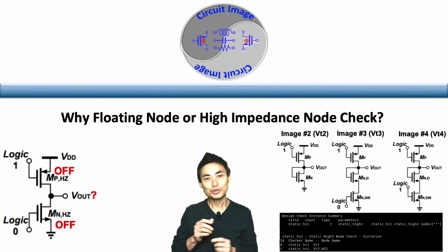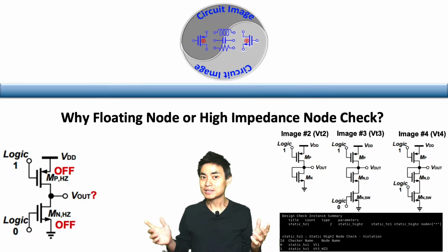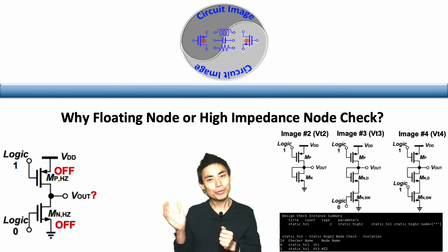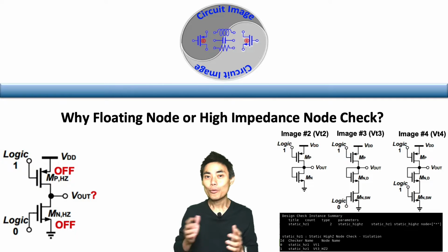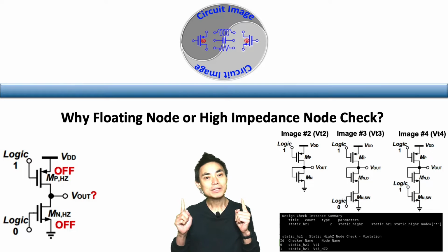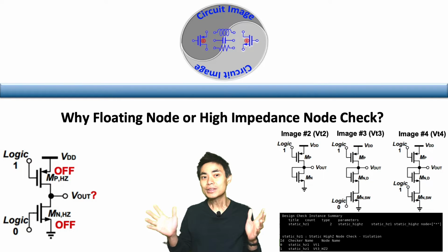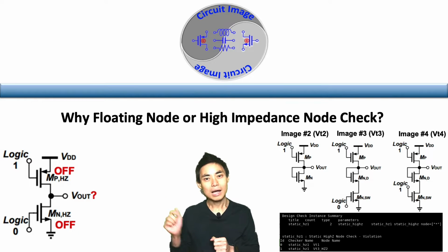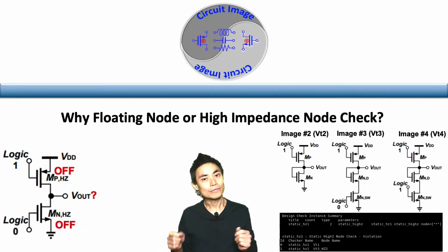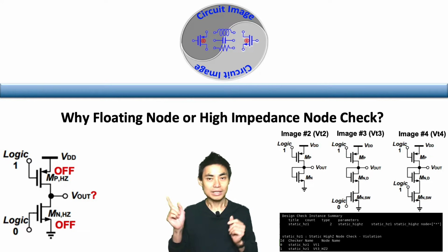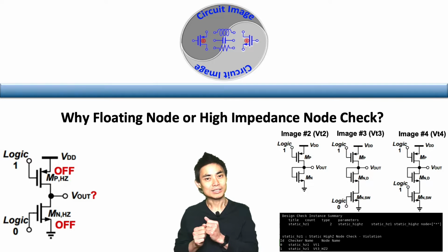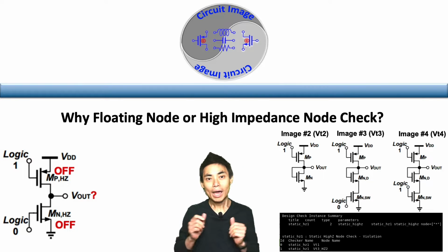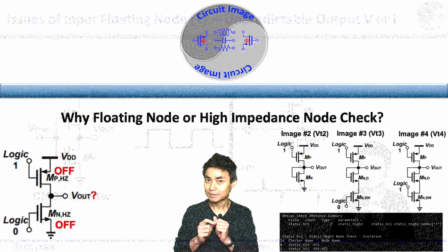As a circuit designer, you may want to avoid any faulty nodes in your design as much as possible. So, hopefully, through this video, you may understand why a faulty node or high impedance node check is a must for you, either through an inspection or a simulation tool. We'll start to show a few case studies of the faulty nodes, which cause issues in the circuit and system. Then, we may show you how the industry tool may help you do the faulty node check.